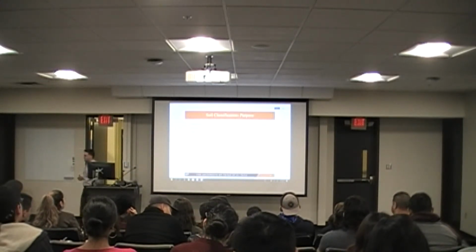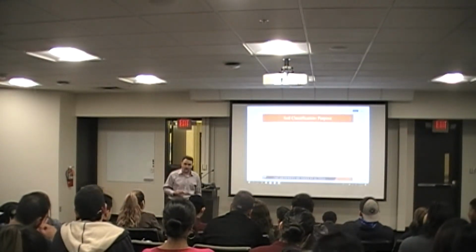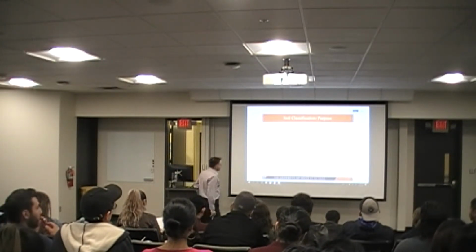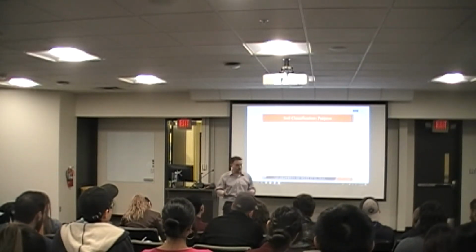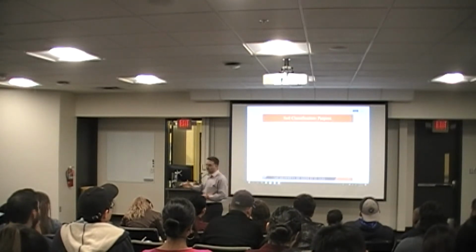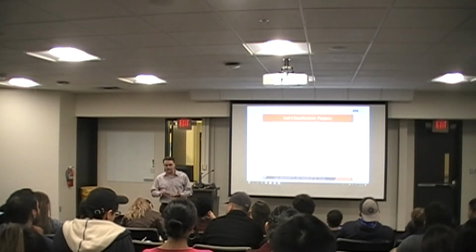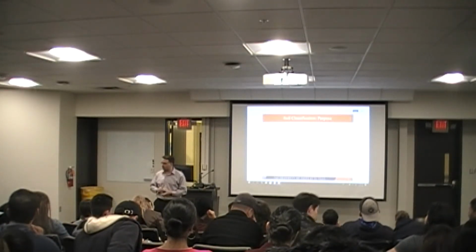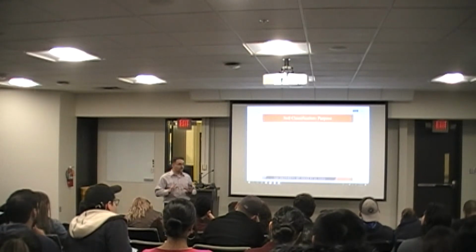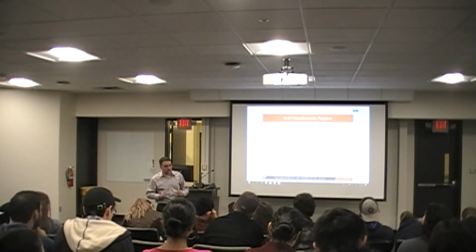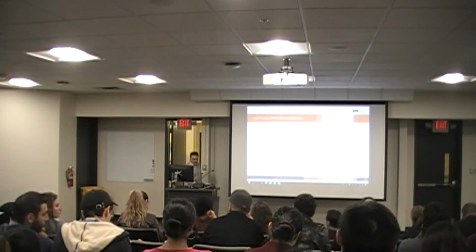And again, remember what the objective is. We want to make sure that we're using simple and straightforward parameters so we can quickly figure out what those designations are. And those simple ones are grain size distribution and information about the Atterberg limits. That's all you need to be able to classify your soils. Beyond that, it's going to be running laboratory tests to get an indication of the stiffness properties, modulus properties, deformation properties, hydraulic conductivity, permeability, and things of that sort. This information doesn't give you that. It gives you a general back-of-the-envelope thought about the type of soil that you have. So this, in very simple terms, is the first step for identifying the soils.